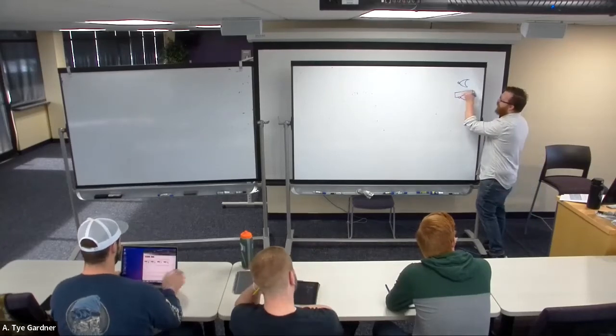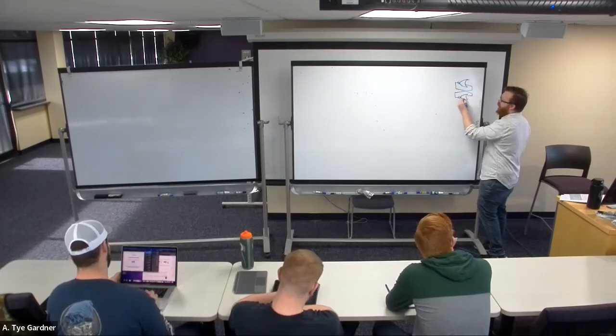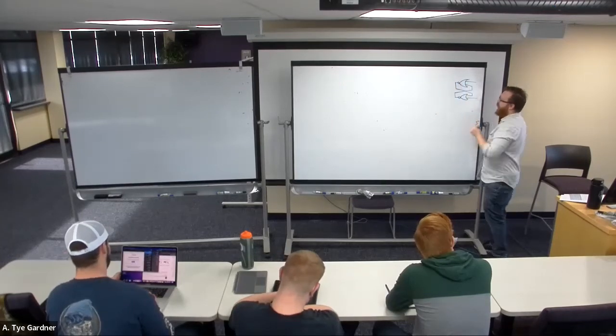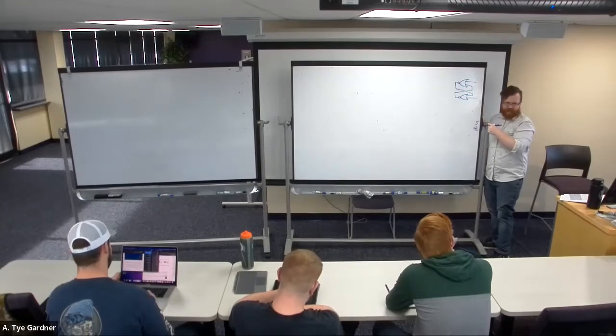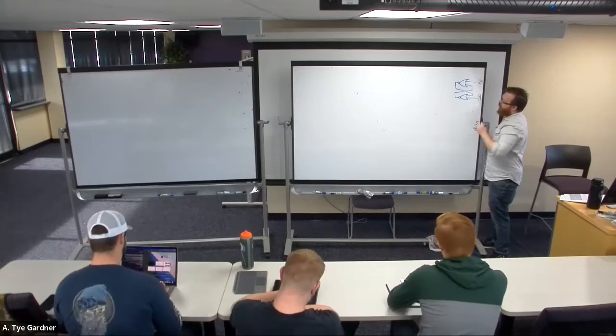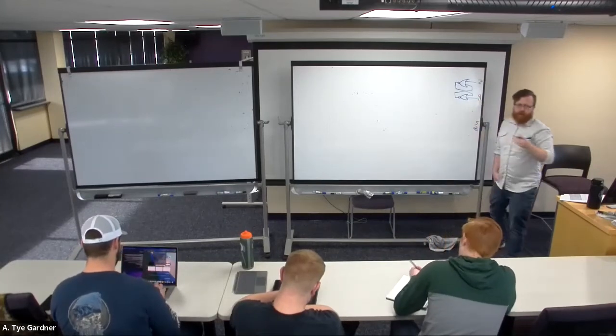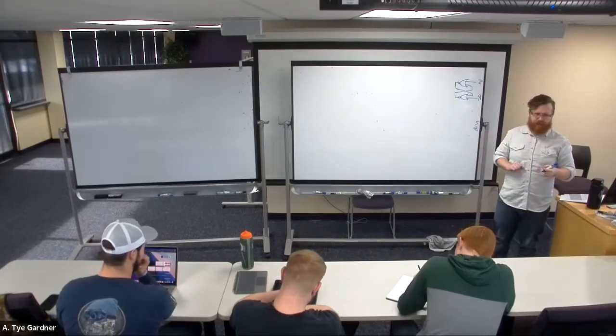So we're going to do what we would also call cross-coupling, like this. Now we can have information that just stays there. And I'm going to call this signal S and this signal R. And then we're going to see what actually happens to these NOR gates, right?